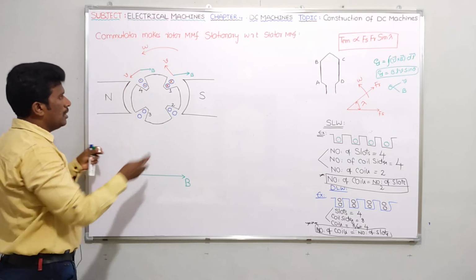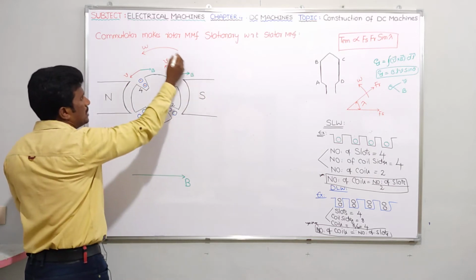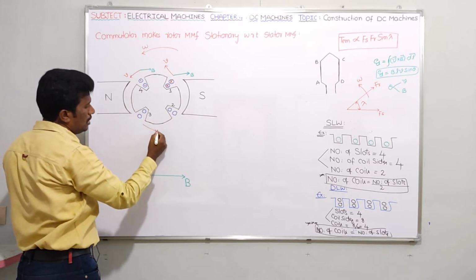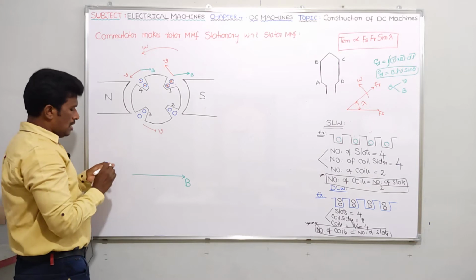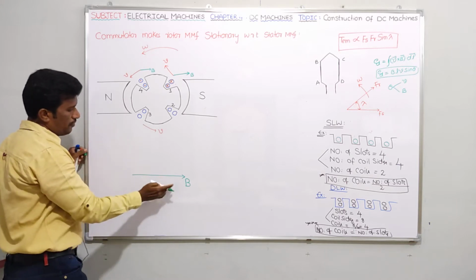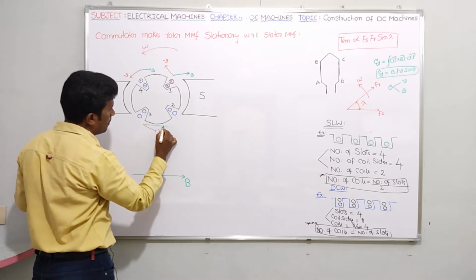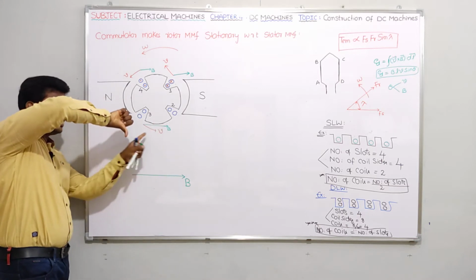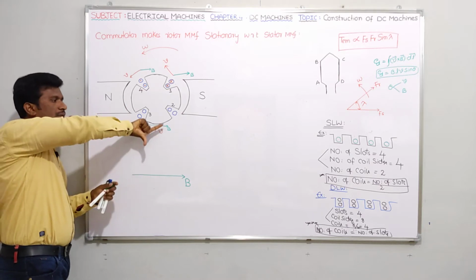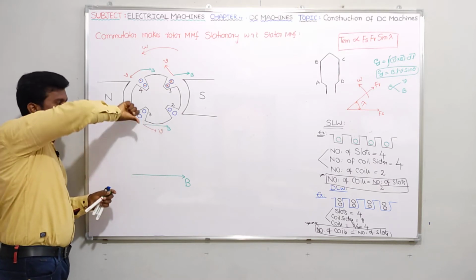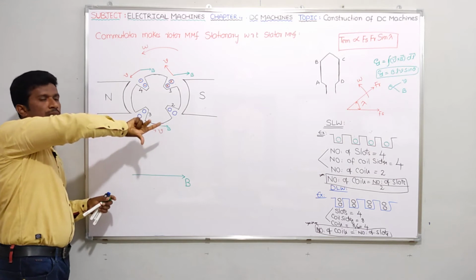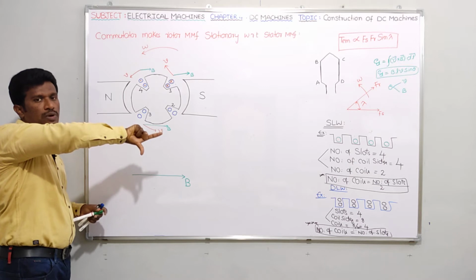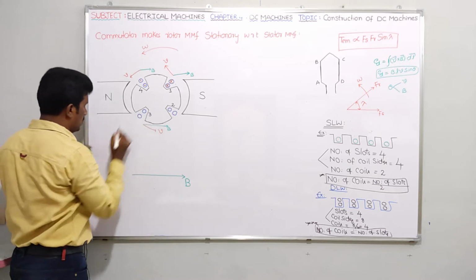Right. Next, once again, if we take anti-clockwise direction at slot 3, this is the direction of linear velocity of the conductor. And what about direction of flux density? It will be like this. Okay. Now tell me, when a moving conductor, this red color, cuts the magnetic field, this green color, an EMF or current is induced in that conductor. Out of the board, guys. Center finger means out of the board. Out of the board means what? Once again, dot. So let me take dot here.